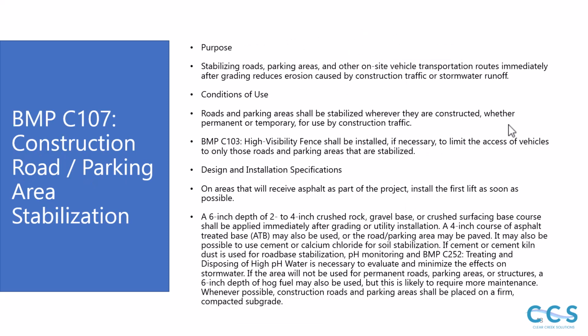Now BMP C107, construction road / parking area stabilization. Stabilizing roads, parking areas, and other on-site vehicle transportation routes immediately after grading reduces erosion caused by construction traffic or stormwater runoff. Roads and parking areas shall be stabilized wherever they are constructed, whether permanent or temporary, for use by construction traffic. High visibility fence shall be installed if necessary to limit the access of vehicles to only those roads and parking areas that are stabilized.